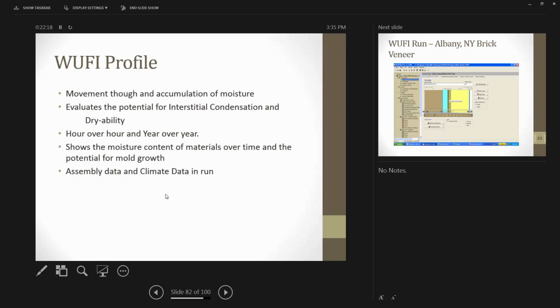And you're actually putting in the climate data for your particular area. We talked about the climate zones previously, and each climate zone has its own data, but you can actually get weather data points for, there's 5 or 6 different ones just in Missoula, so very specific weather point data. It's got heating degree days, cooling degree days.